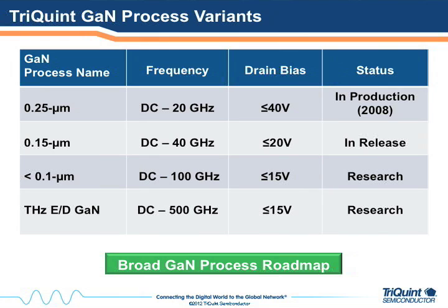It won't only support the Ka band power, but also wideband, low noise figure LNAs. So we'll be producing a variety of products using the 0.15 across frequency, across power levels, and world-class LNAs with it as well. And then even extending the frequency coverage up through W-band, which we have a contract for, as well as up through 500 gigahertz for high-speed logic applications. So I'll get into that in the next slide.